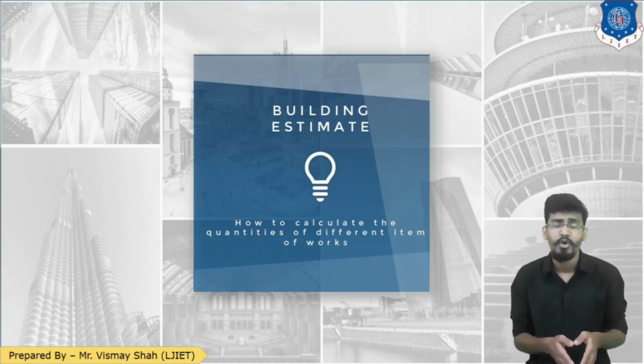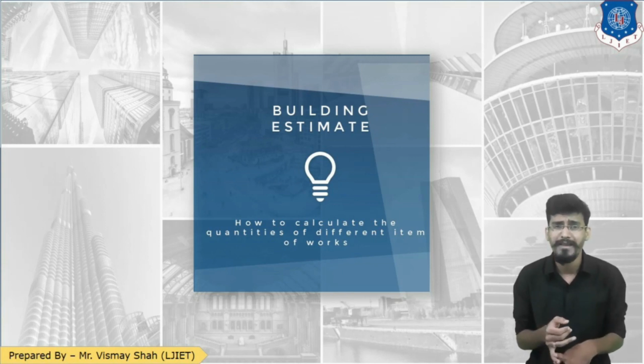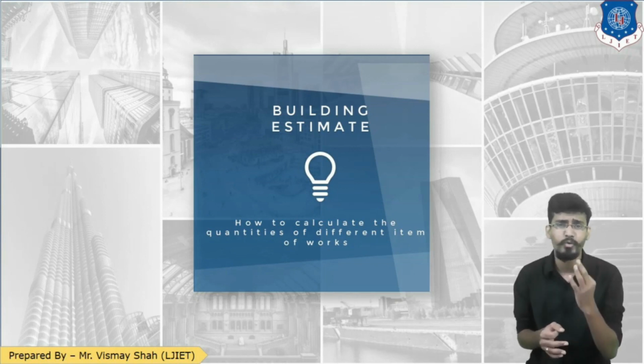There were two types of structure: load bearing structure and frame structure, and we have already discussed that we are going to see numericals most often on the basis of load bearing structure. Then we discussed the abstract sheet and measurement sheet, and we saw the format of the abstract sheet and measurement sheet. Then we saw the three methods for quantity calculation. There were three methods: centerline method, long wall and short wall method, which is also known as out to out and in to in method, and third was the crossing method. So we have discussed three methods.